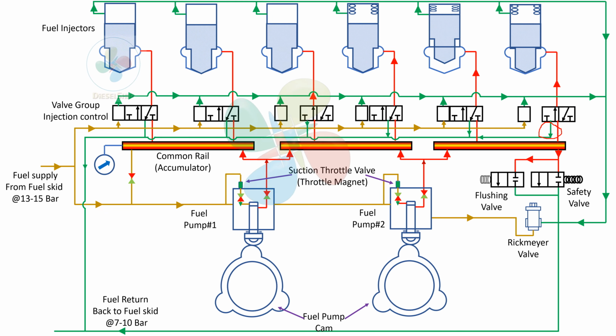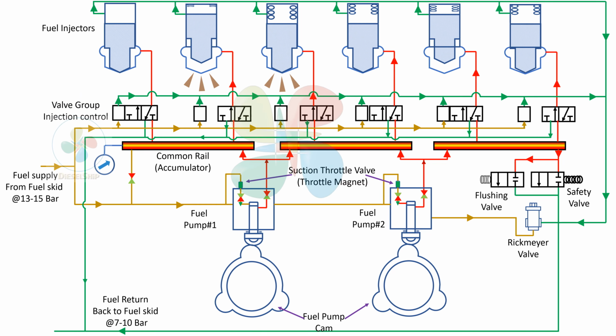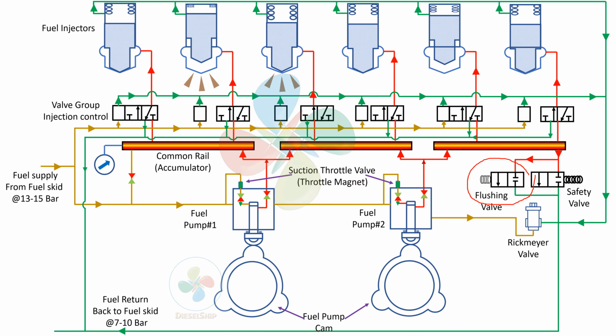This is what happens when the fuel injection terminates, right? So this is one of the very important factors. And in this video, in the beginning, I forgot to show you the flushing valve is closed, right? As soon as the engine starts, the flushing valve closes. That is a very important factor.